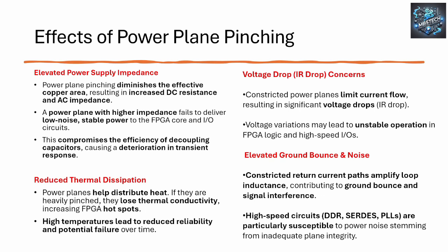We tend to design a thermal impedance in. I'm not talking about electrical impedance now, a thermal impedance, such that it draws the heat away from sensitive parts that get hot. But if you get your via power plane clearances wrong, you essentially start to remove all that copper, and then you haven't got the low thermal impedance that you think you have. Okay.